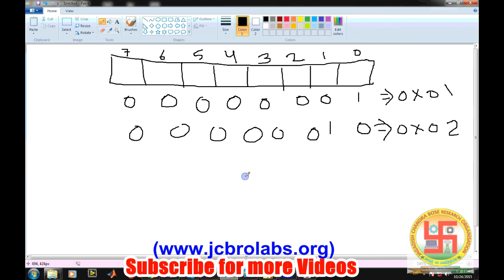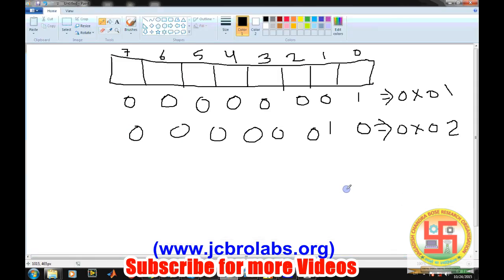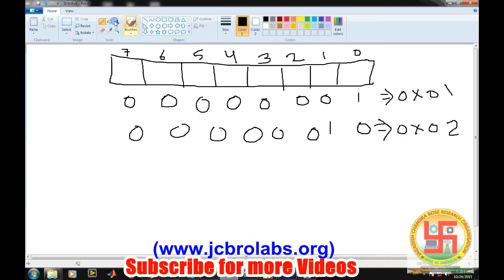So we just saw the response of our program, which we wrote in Keil, and how it works on a real machine. Till now we connected just one DC motor, but if we look at the connection diagram of this motor driver IC, we can connect two DC motors at a time, and they can be connected very easily. Let's say one motor will be connected to pins 0 and 1 of the microcontroller, and another motor will be connected to pins 2 and 3.